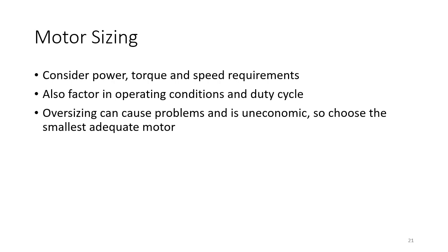So oversizing can be problematic in itself, but the key issue is that buying a bigger motor than you need costs more than you need. Another factor there is efficiency. A bigger motor, because it's not operating at its 100% load, becomes less efficient compared to operating a smaller motor at 100%. Because the majority of the operating costs of a motor are actually the power over its lifetime, choosing a bigger motor can be extremely uneconomic, not just because of the extra cost of the motor, but because of the extra cost of having to provide electricity to the motor.